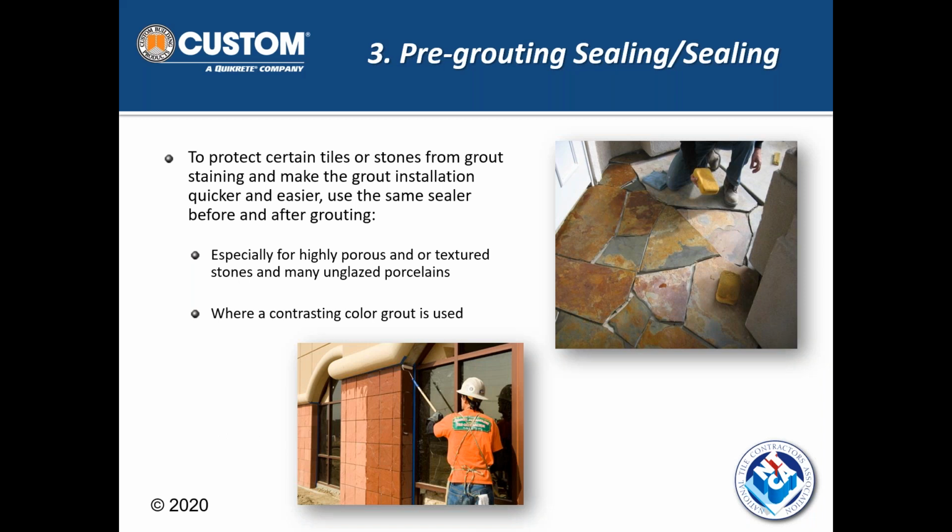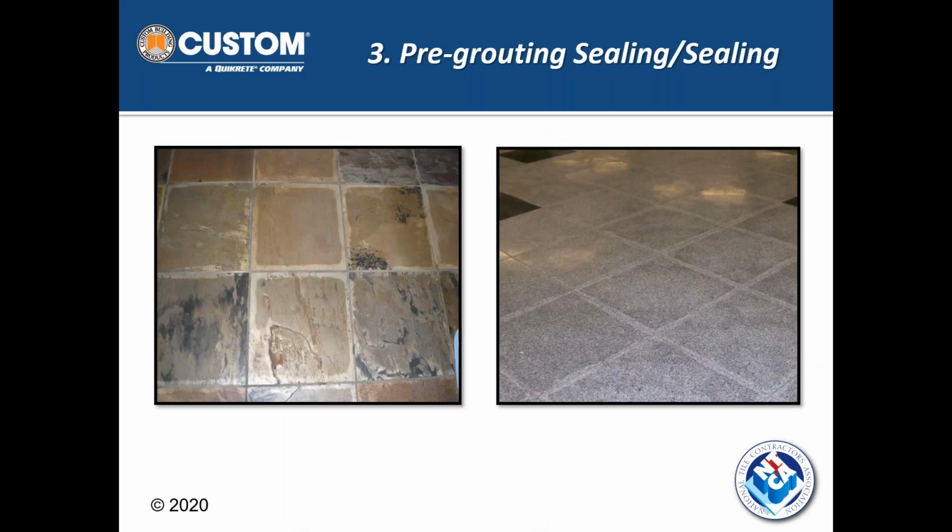All right. So obviously for the more porous tile or stone, we've talked about that. And again, where a contrasting grout color is used. So here's two different pictures of color enhancing sealing being done beforehand. What I just said a minute ago, here's what you don't want to do: not pre-seal, and then go back with a color enhancing sealer.